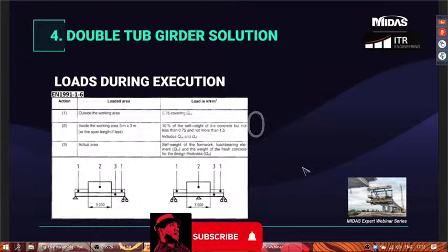Eurocode 1991-1-6 prescribes some loads to consider for the casting phase. Mainly, we have the weight of the fluid concrete, the presence of workers and facilities, and formworks. This can be theoretically considered as a moving load because we don't know the most onerous position for the working area. In MIDAS, we could do this, converting this moving load into a static load through a specific function.